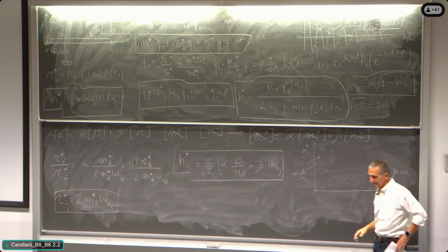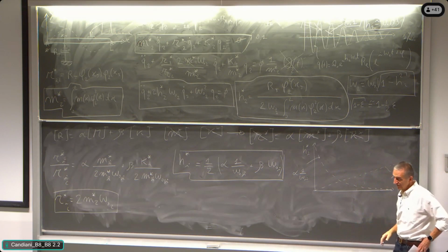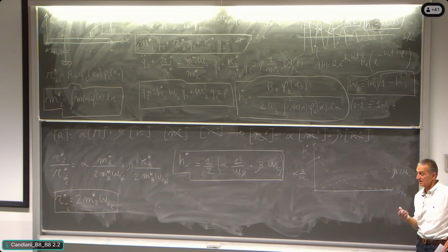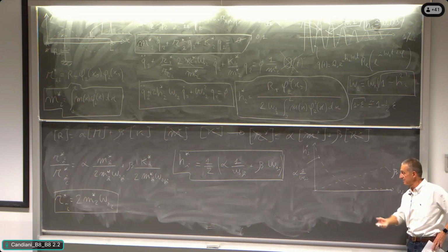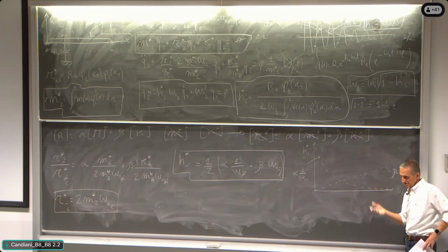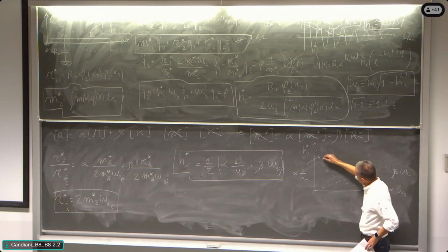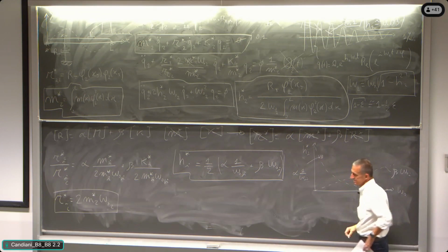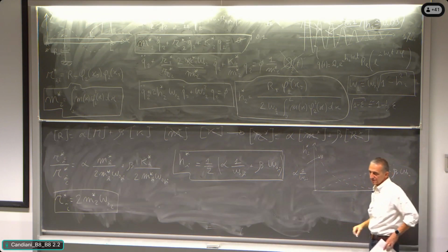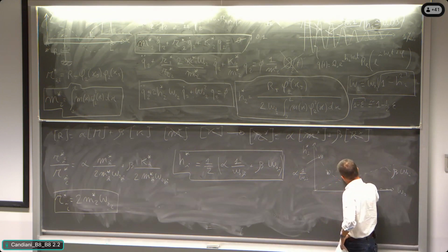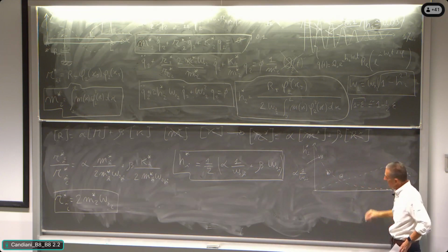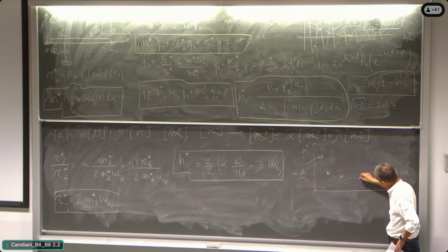And so if we have access to a structure and the structures are monitored, we can learn from the real world in which way the structures are behaving, and those modelings are coming from the monitoring of the real structure. It could be that we are measuring the non-dimensional damping of the first mode, then the second mode, the third mode, the fourth mode and fifth mode, and so on.